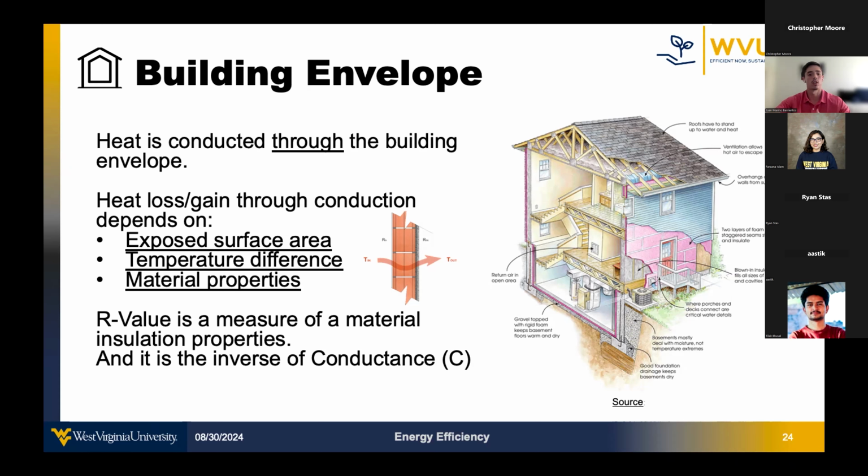So there are a lot of materials that are being used for constructing walls, roofs, and windows, and picking the best ones with better insulation and R values, which will be discussed here in a little bit, is critical. Different materials have different levels of thermal conductivity. For instance, metal conducts heat much more efficiently than wood, leading to a higher rate of heat being lost or gained.